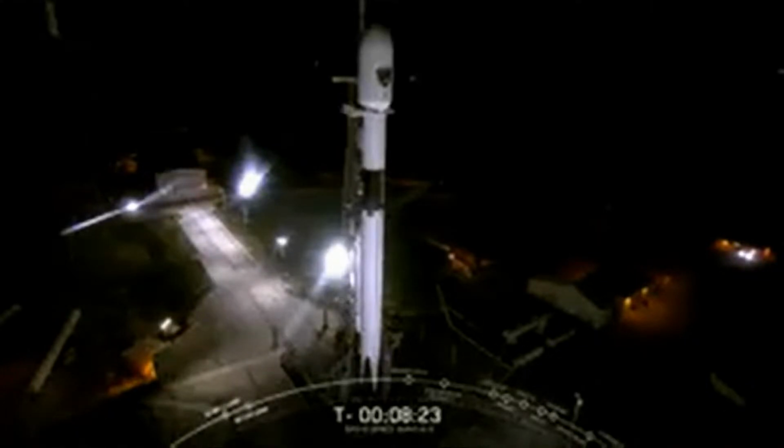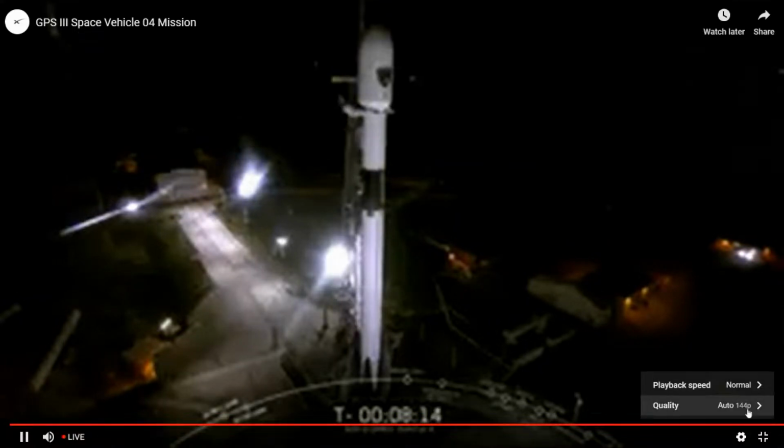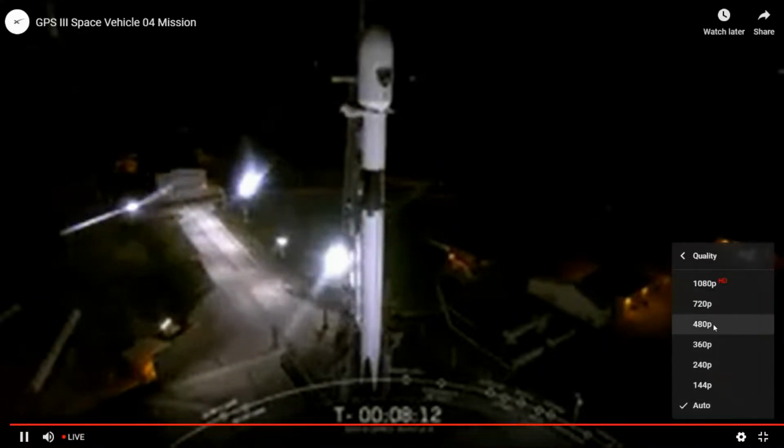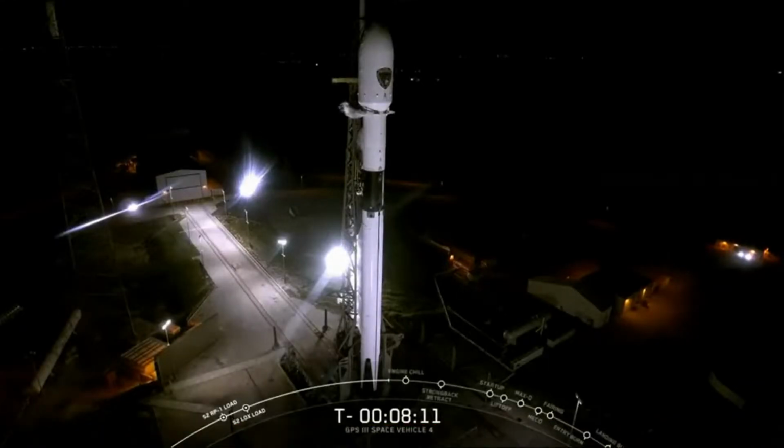Our fuel is a refined form of kerosene known as RP1. Our oxidizer is super chilled liquid oxygen called LOX. We chill it well below the boiling point so we can load more onto the booster, as well as avoid the need to continue topping it off to make up for losses due to propellant boil off. Now currently the second stage that you can see on the screen, just above that black inner stage cylinder, is fully loaded with the RP1 kerosene fuel.